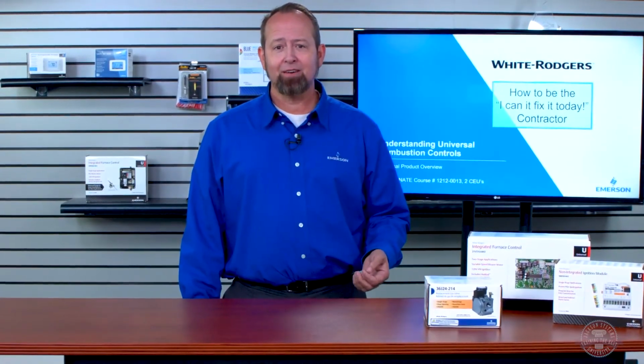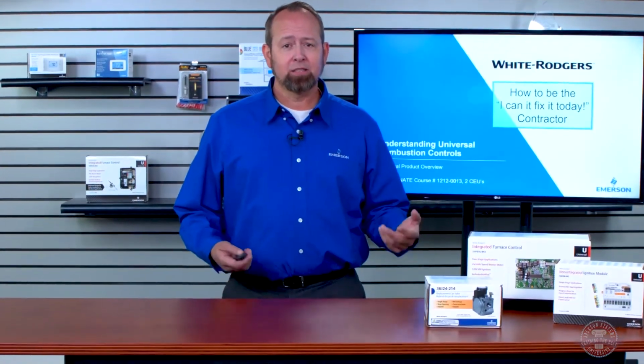There are a lot of universal options out there today that really give you the ability to change the product and put the new part in while you're there, saving yourself that trip to the supply house. So we're going to go through understanding universal combustion controls, some slides showing what we have from Emerson White Rogers for product offering, but also giving you some pointers along the way and a little bit of basic understanding of how different components work as well.